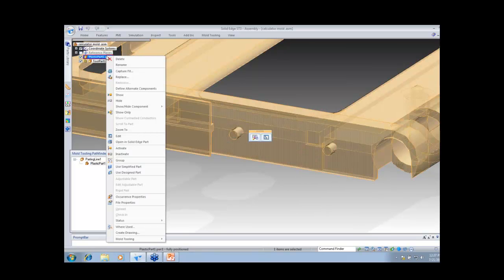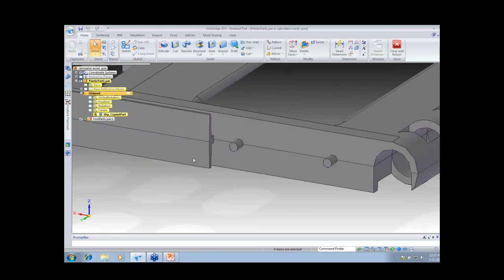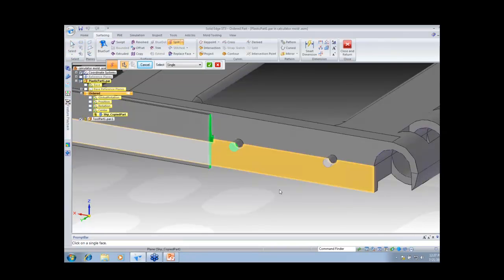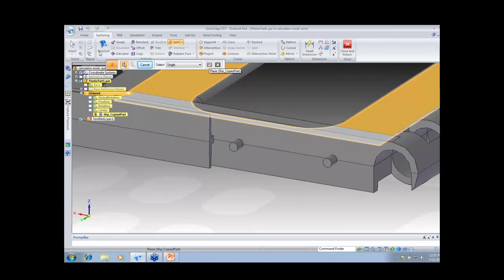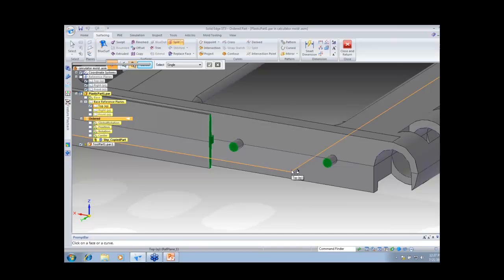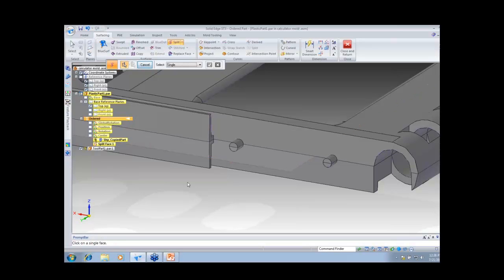Again, what I'm going to do is add it inside the part, and that will open up in the Solid Edge part environment. Here I'm going to use some surfacing capabilities to divide the face. I'll use the split face command. This is very powerful. I just select the face, hit accept. Now I can give it a direction for the split. I'll turn on the reference plane for top, and use this reference plane to split the face. I select this face, hit accept. It divides along this reference plane, as you can see. It divided all three faces.